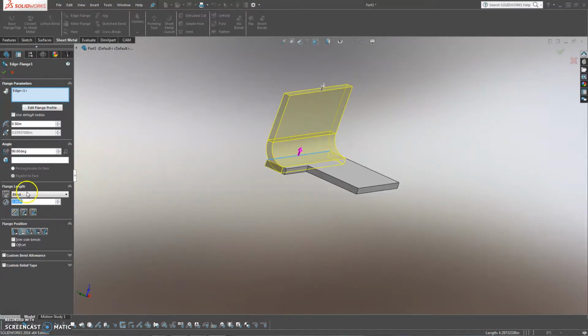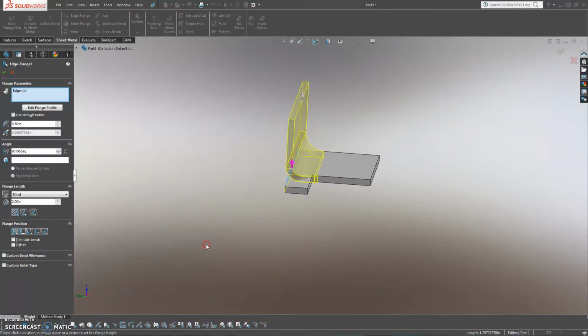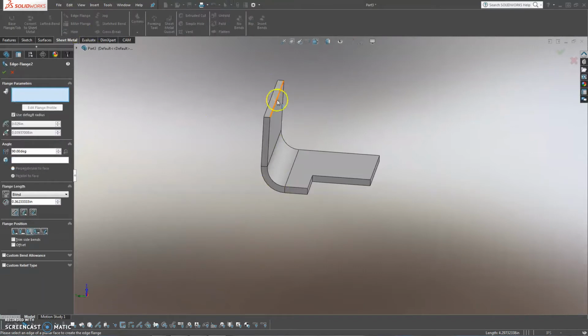Other important things, you can adjust how that dimensions, those 2 inches, and then also how that bend's going to be. Is it on the edge? Is it part of it? Does it line up with this edge here? Does it not? Things to consider when bending. We're just going to pick this one right now. Hit the green check.